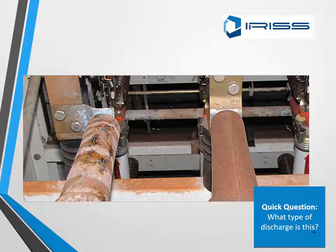So a quick question for you all. What type of discharge is this? Well, I've left a little gap, but obviously as you can see, we've started off with a corona. Why do we know it's the corona? Because as you can see, we have the white powder. But then it's now also gone on to something else, and that's correct, that's tracking. You can see the little carbon residue as well.